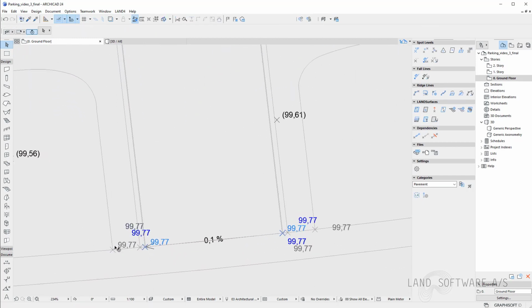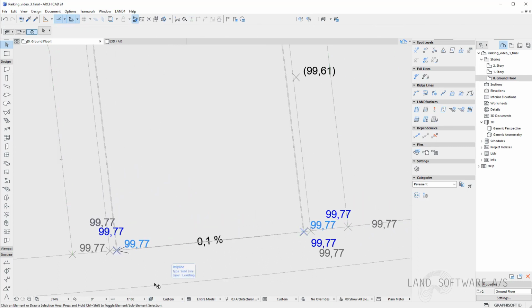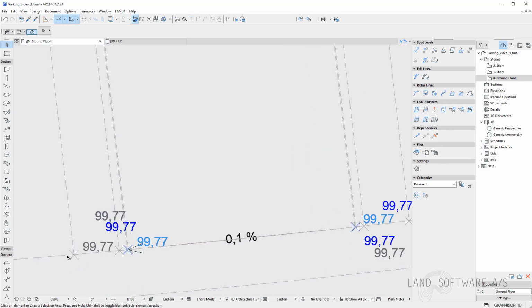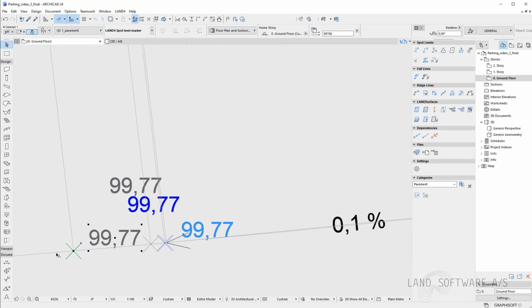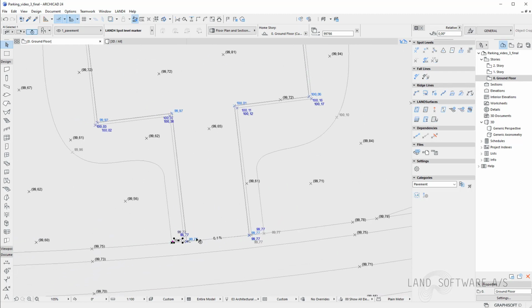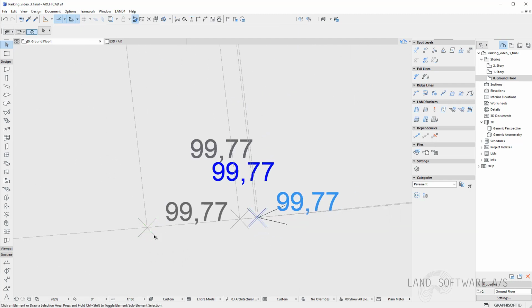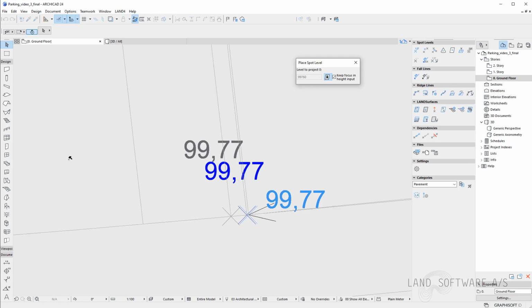So once I'm done adjusting the geometries for the ridge lines where they meet the road and the spot levels, what I now need to do is make sure the height of the spot level at the junction with the road is the same, because we have basically moved it 5 meters along the road. So now I can basically select the spot levels at the road and I can just delete them. And now I make sure I'm in the right category, and now I can place new spot levels, which I am basically reading from the surface of the existing terrain. And I can place new ones.